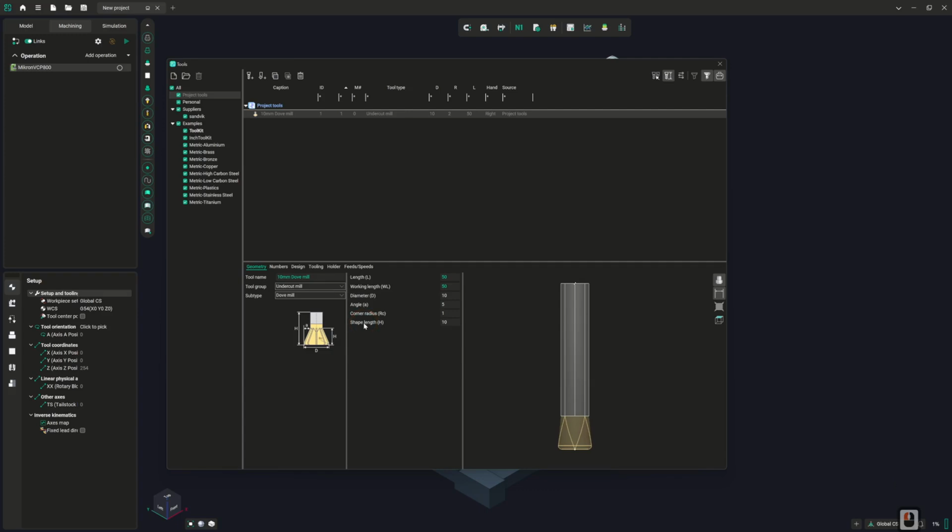Now, this is probably best described as a dovetail cutter in this instance, but we do also have multiple different types here. This is where the subtypes really come into play. So we've got things like larger slot mills and everything for doing T-slots, lollipop mills for any kind of rounded groove that needs to go in, two-angled mills, again, if you want to deal with a doubled taper or you need to produce a paired set of V-slots opposing each other, round grooving, sharp chamfers, rounded chamfers, indexable chamfer mills as well.